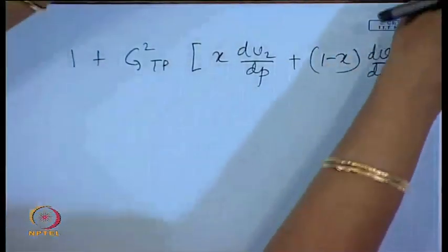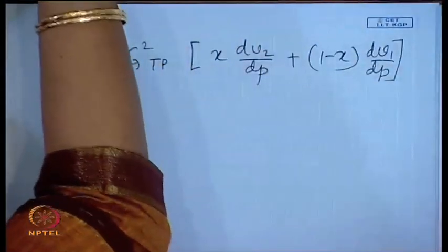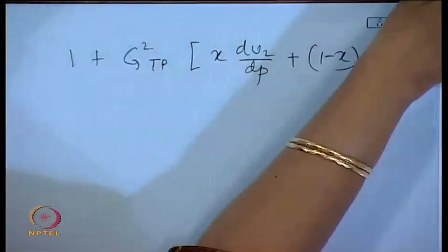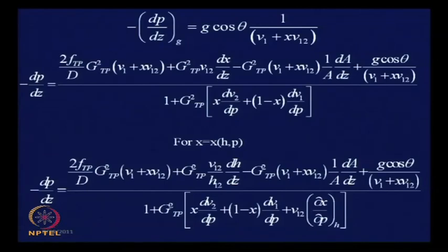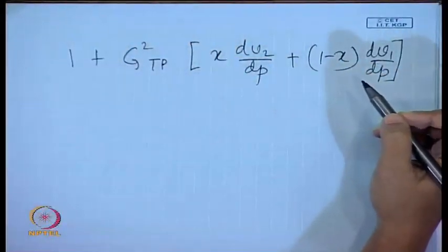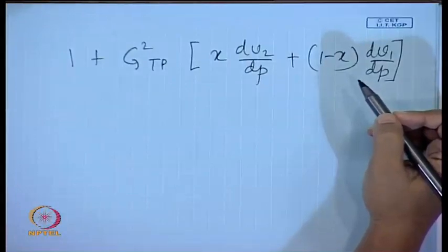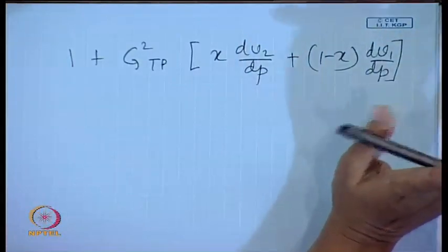Okay. Now, the point is, if the denominator under that condition had corresponded to the choked flow condition, then in this particular case also, this denominator should correspond to a Mach number of two phase flow under homogeneous flow conditions. Do you agree with me? Isn't it? It is just simply fluid flow. We have simply done what we had done for the compressible flow case. Agreed? What extra have we done?